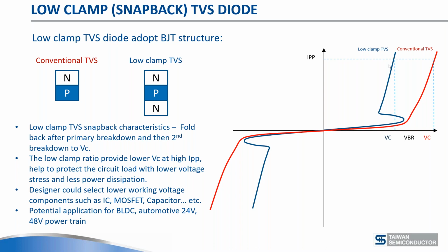And the second one is, of course, it has a lot of downstream savings here. What happens here is normally you take a 24 volt, 27 volt here, and everything, for example, in automotive is 40 volt rated because that's what the clamping voltage says here, and that's what you want to do. You don't want the MOSFETs or the ICs, power management ICs or whatever is in there going avalanche or anything like that. Obviously here you can get a lower clamp voltage and you can use lower voltage CMOS behind the TVS here. I think in this case you can securely use 30 volts here. That's what the device is doing here.